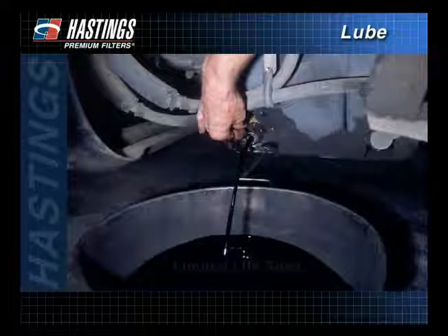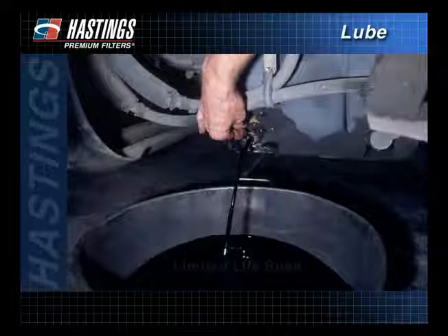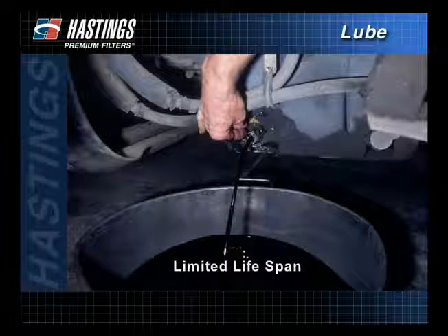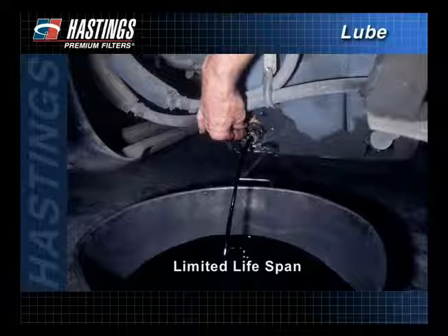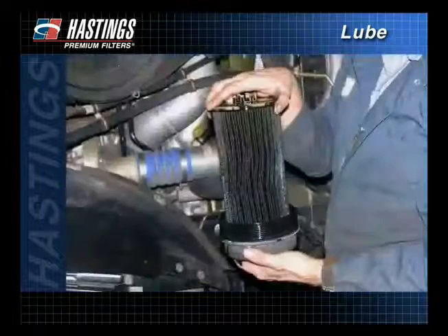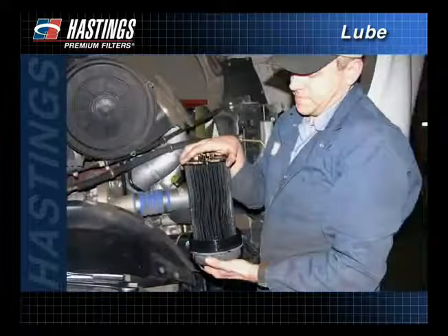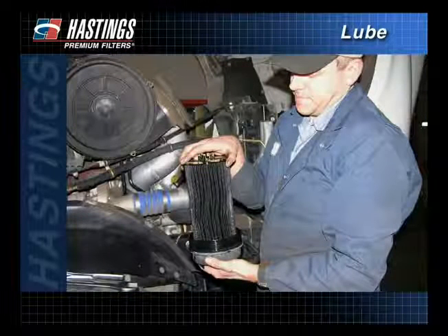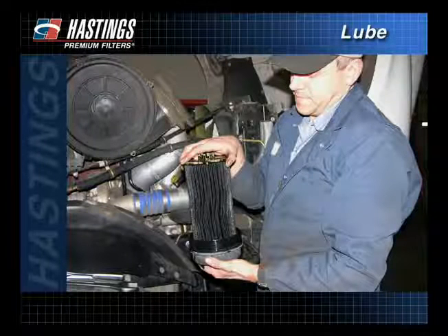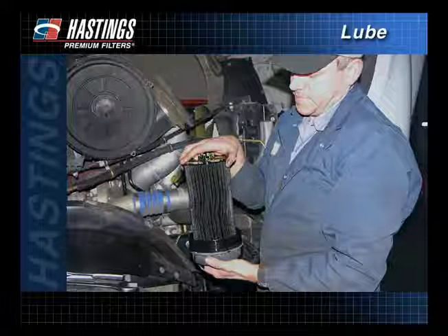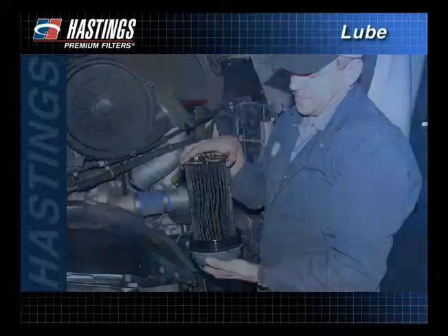Keep in mind that although many improvements have been made in oil quality and additives, lubricating oil has a limited lifespan. Filters also have a limited lifespan. If they are run beyond their capacity, they can no longer provide protection to an engine. That's why establishing drain and filter change intervals to incorporate economy with maximum protection is ideal.